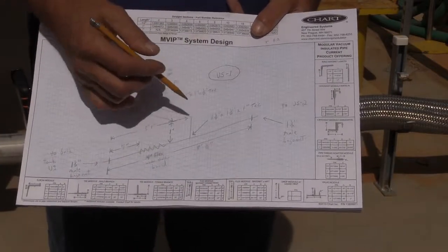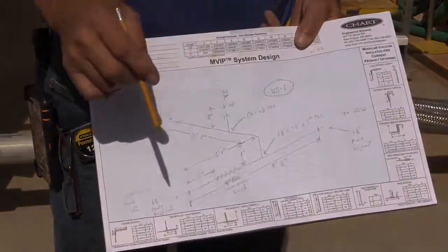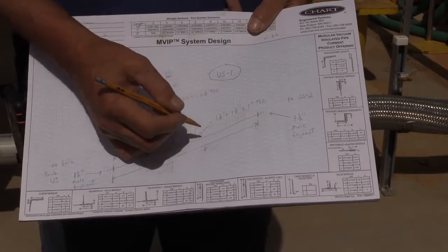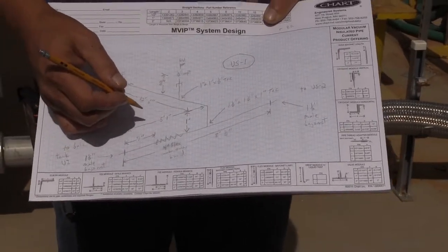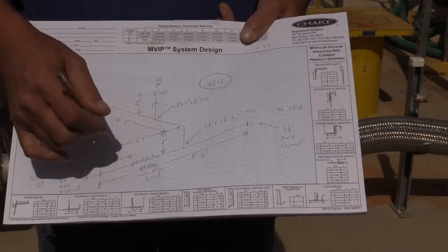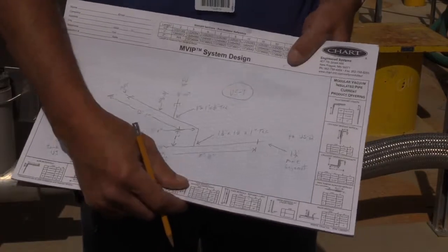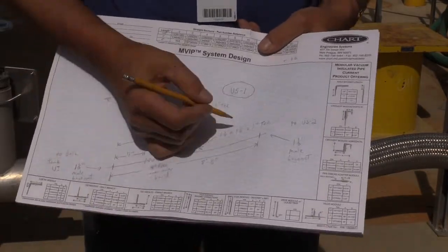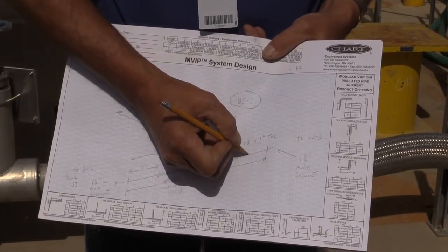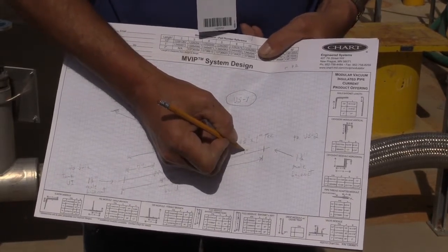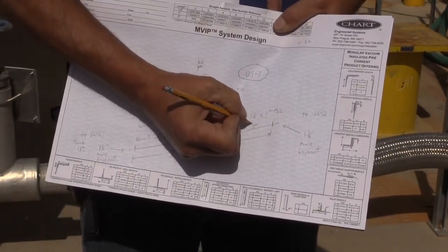Another thing, all of these systems have vacuum pump out ports that are put on the section. If it is not detailed on the drawing, the draftsperson who puts this together will choose where to put that pump out. So if we have a specific place we need to have that pump out, we absolutely should put a label on the drawing and draw a pump out in here, and we should call it a pump out.